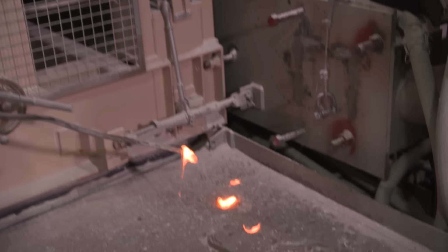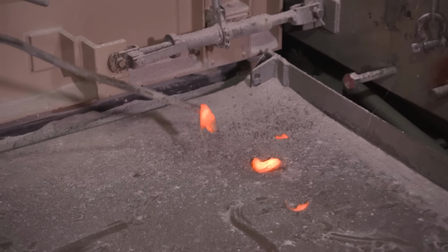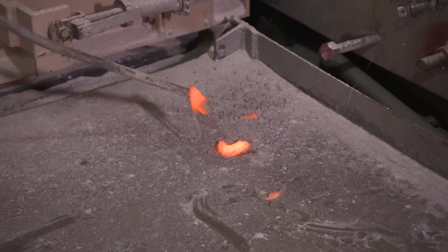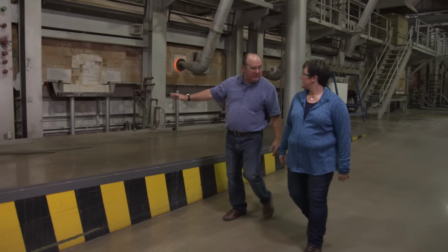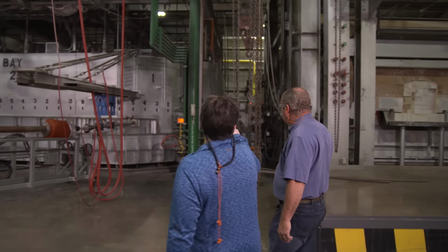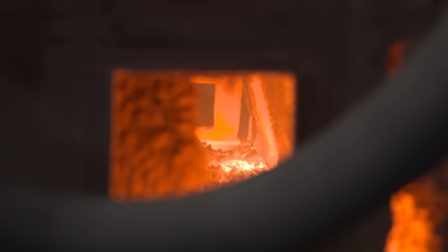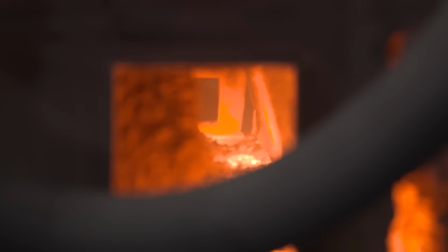Oh, look at that. So it's already turned to goo. It's already turned molten. So this is all filled with molten glass? Yes. And when the glass comes to the canal, at this point it flows into the tin bath. In the tin bath, we melt tin. Varies between 2 and 4 inches in depth. As the glass pours in, it's about 1/4 of an inch thick. It spreads out over that molten tin.